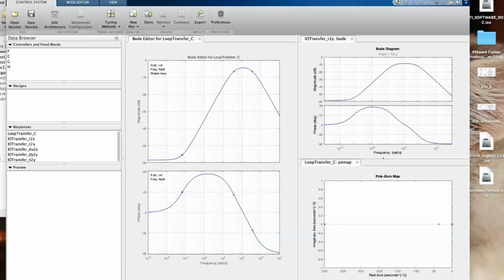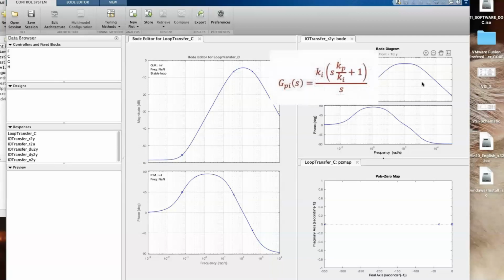So we have to select the values of the Kp and Ki for the PI controller so that the crossover frequency occurs at 12.56 kiloradian per second, or the closed loop bandwidth of the torque is at 12.56 kiloradian per second. As I mentioned in my previous tutorial video, when we add the PI controller to the loop, we add a 0, an integrator, and a gain. We have a choice of selecting the locations of the 0 for the PI as well as the gain by manipulating the values of Kp and Ki. So let's do that now.